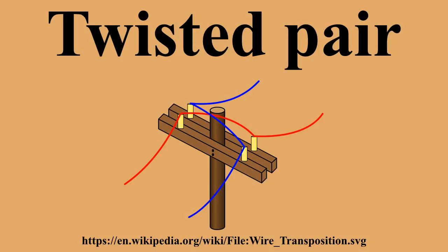Cable shielding. Twisted pair cables are often shielded in an attempt to prevent electromagnetic interference. Shielding provides an electrically conductive barrier to attenuate electromagnetic waves external to the shield, and provides a conduction path by which induced currents can be circulated and returned to the source via ground reference connection.